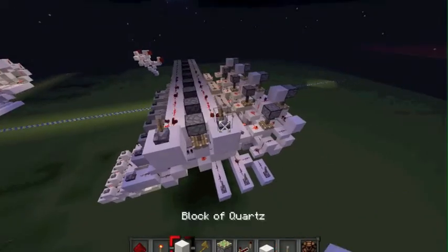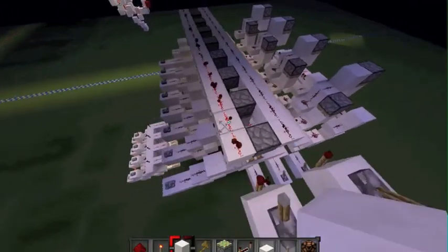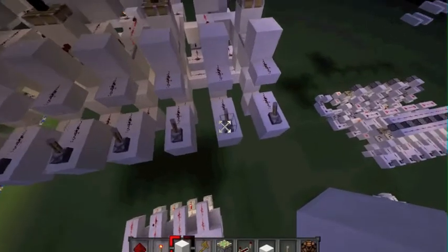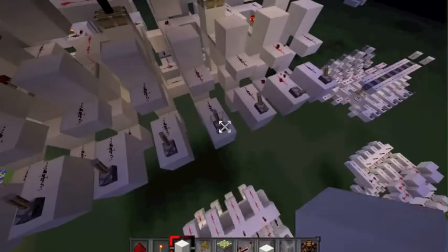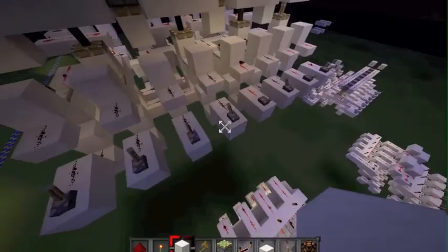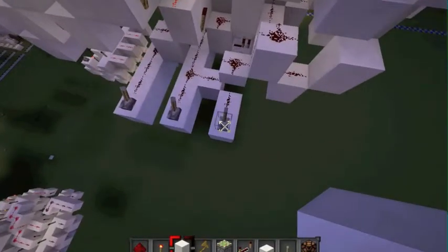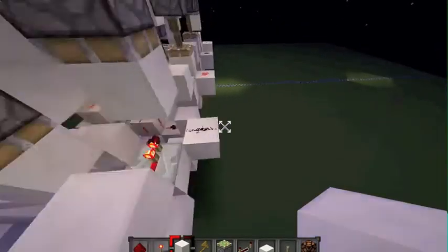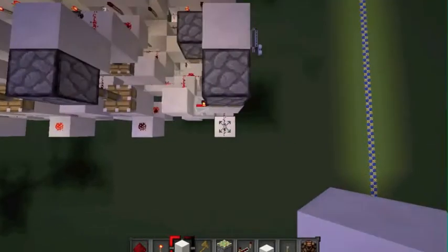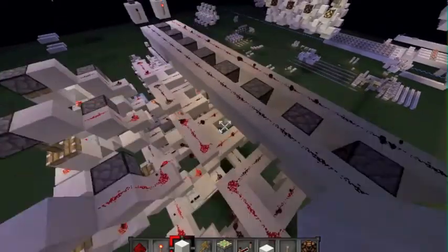If you want to see subtraction, because I didn't show it earlier, let's invert this input. So that means that this input right here is inverted. So this is the negative. This needs to be the negative one. So -3 plus, guess what? 1, 0, 1, 5. 5 minus 3. And of course we have to carry in also because it's using 2's complement right here. You can't do 1's complement with this. We get 2. And yeah, since that's on, it's positive 2.